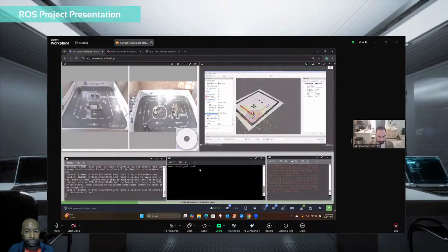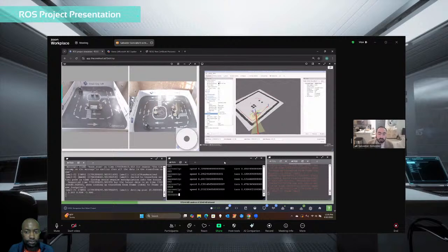Great. Turn down the speed, and then I'm just going to rotate, and then we should watch as the program converges on where it believes it is. It's using something called adaptive Monte Carlo localization, which is comparing sensor data to map data, and it's using a probability distribution based off of Bayesian math to come up with this estimate of where it thinks the position is. And we see how all of these points, which were everywhere, are now starting to converge on where we expect to be, which is good because this is nice and focused. Right.